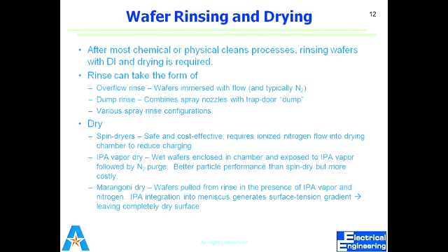Actually, what we did in the lab was because these are rinse-dedicated processes. They are in the fab. We don't have that in the lab, so we rinse it manually. That's why, if you remember, after taking it out of that DI water, I asked you to rinse it in DI water manually, because we need fresh DI water to clean the surface. After one chemical process, the cleaning process, when you put it in DI water, some of the contamination would still be inside that DI water. So that's why we need to put up or flow new DI water on the surface of the wafer.